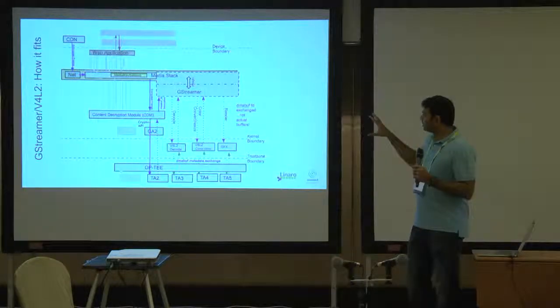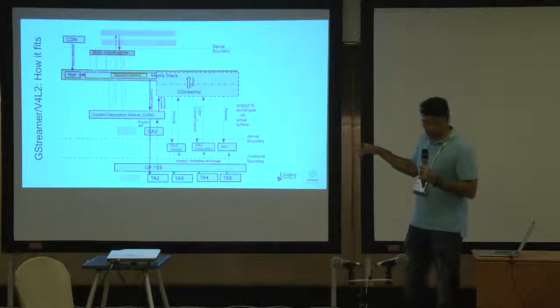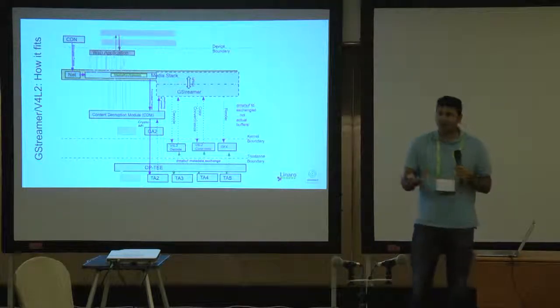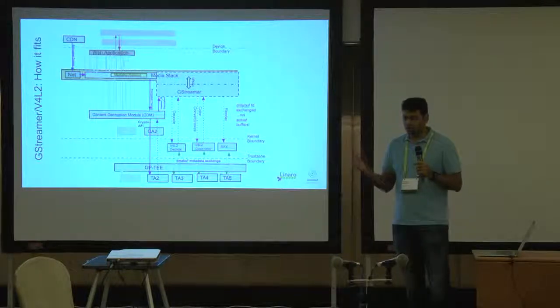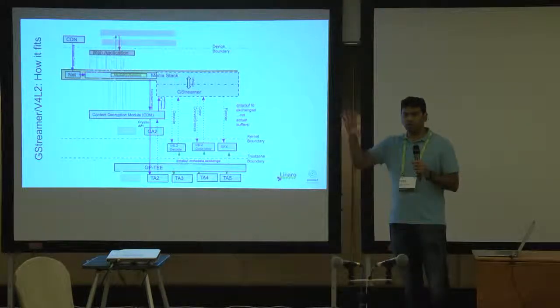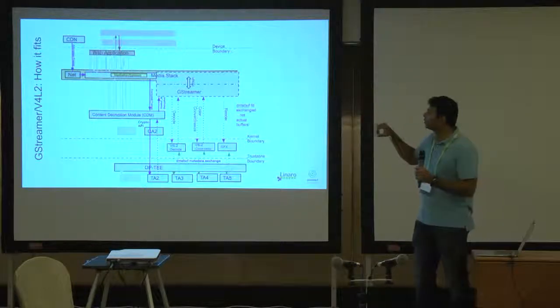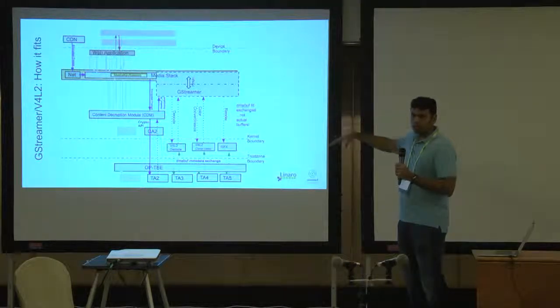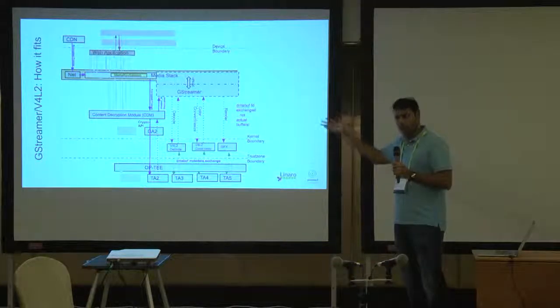And the other thing that is not in any of these pictures is where do you get the buffers from, right? So you could use an allocator, right? For the first thing, you probably have to use something like a TrustZone address space controller to block off a certain area of the memory and allocate buffers from that pool, right?